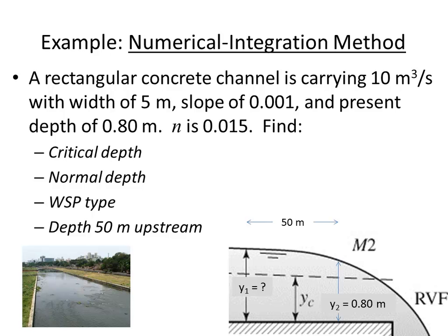Okay, we solved Manning's equation using Excel in class last time. It took us a little bit longer than I expected. I guess it's good that we got our practice. In this case, I'll just put the magical solver, assuming that there's some really quick, easy way to find the normal depth, maybe with the calculator or something, 1.124 meters.